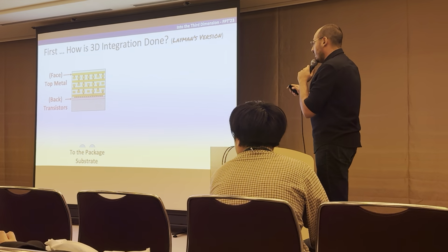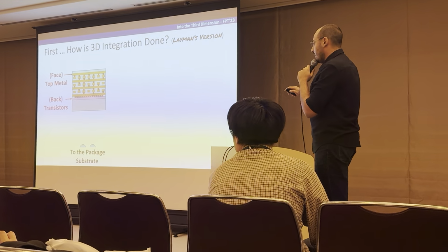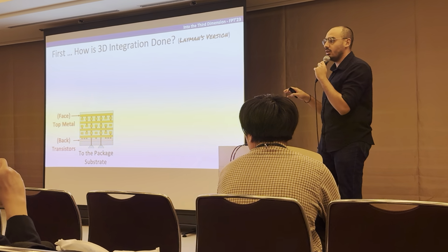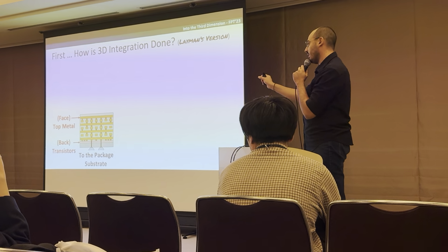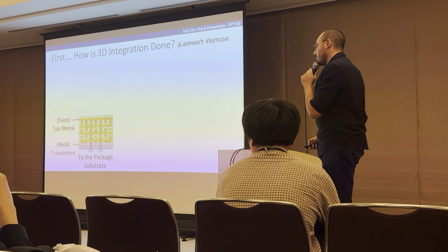Instead of doing a flip chip where you connect the top metal layer of the chip to the C4 bumps that go to the package for power and IOs, you thin down the bulk silicon of this chip and then connect the lowest metal layer of the chip to the C4 bumps using through silicon vias, which are the black columns I'm showing in the figure.